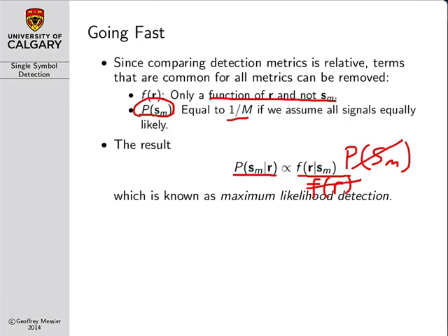And so rather than calculating the exact value of posteriori probability and then doing a relative comparison with those probability values, instead, since we know that the R distribution and the a priori probability don't really affect our relative comparison, we ignore those two terms that I've crossed out, and we instead just choose the transmitted signal vector that maximizes our likelihood function.